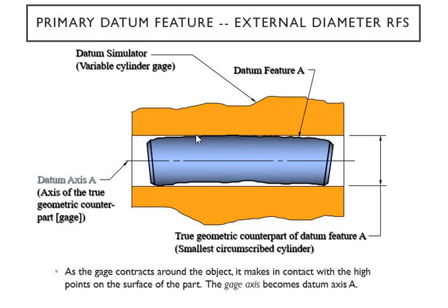When you measure against the gauge, this measurement from here to the gauge, from there to the gauge, that's your datum axis, the reference axis that you measure from, and it has to be almost the same. So that would be the center of it because that's the axis. The measurements are done that way. Since you measure the gauge, it's the same as measuring that surface. So in real life, you have a datum axis right there, and every point on the surface of the blue cylinder is going to be measured that way to verify. And you bring all of your tolerance variable zones right in there to measure with.